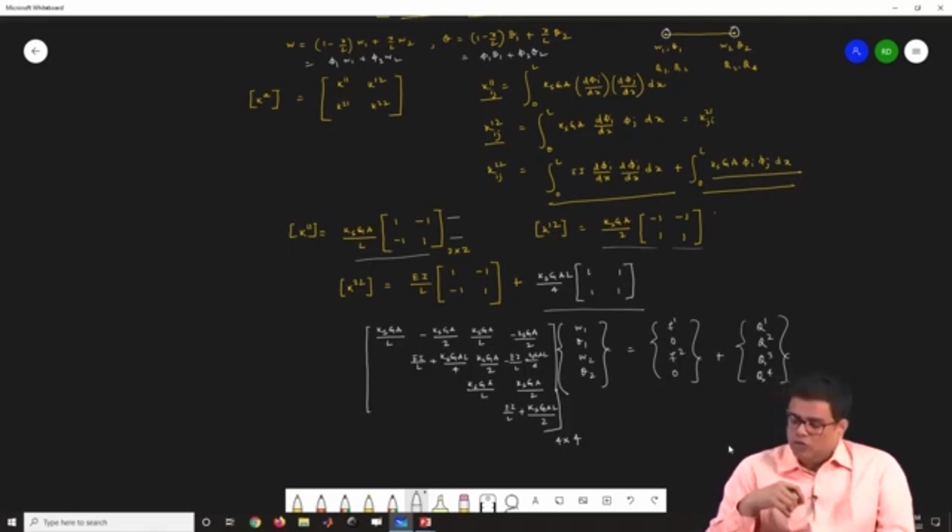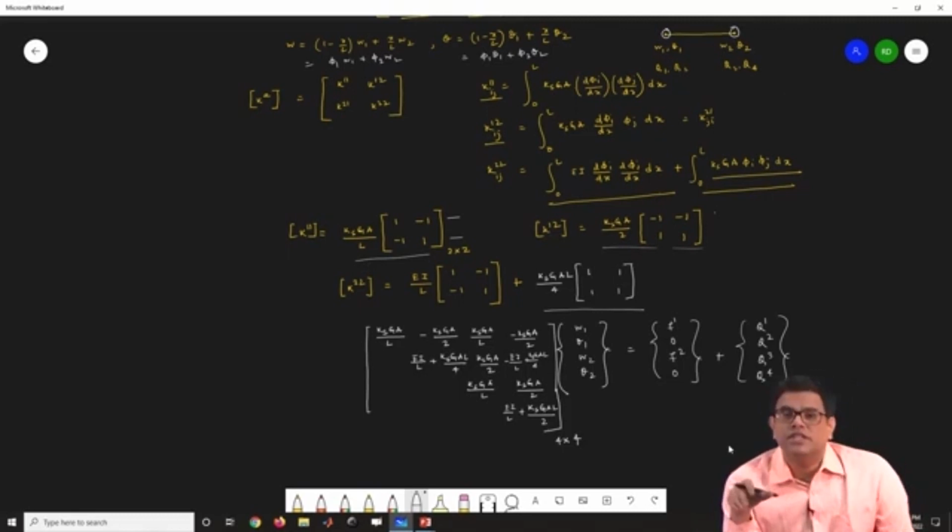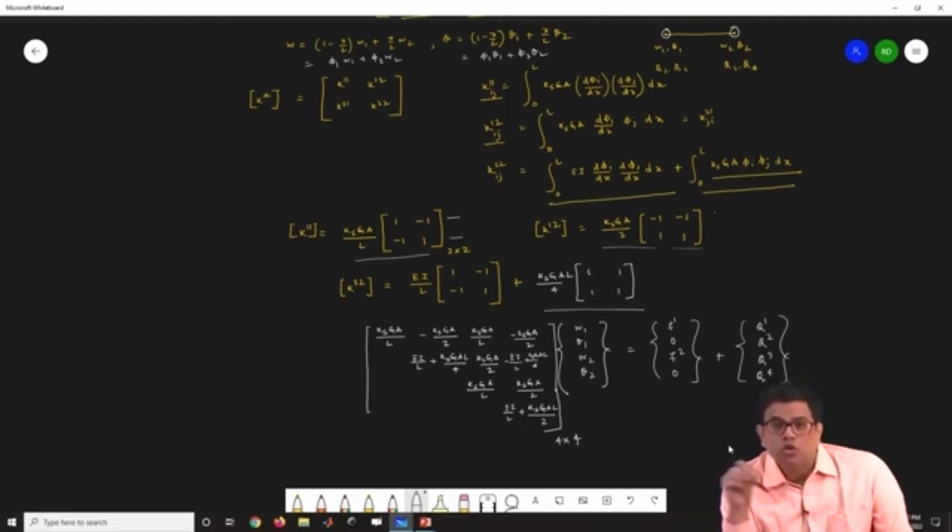So we'll just stick to the reduced integration, by which, by numerical tweaking or considering a different numerical rule, we can compute the finite element stiffness matrix, which essentially considers here, for instance, the shear strain energy actually consistent with the theory in the case of a thin beam.